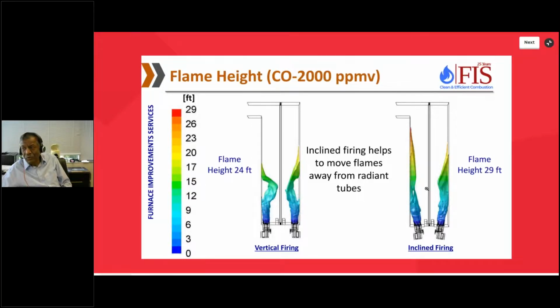You see, the beauty of the radiant section is that it does not need a medium. If you are looking at radiation, we are able to receive heat from the sun even though it is millions of miles away from us, so it does not need a medium. Similarly, you don't need to keep the flames closer to the tubes.